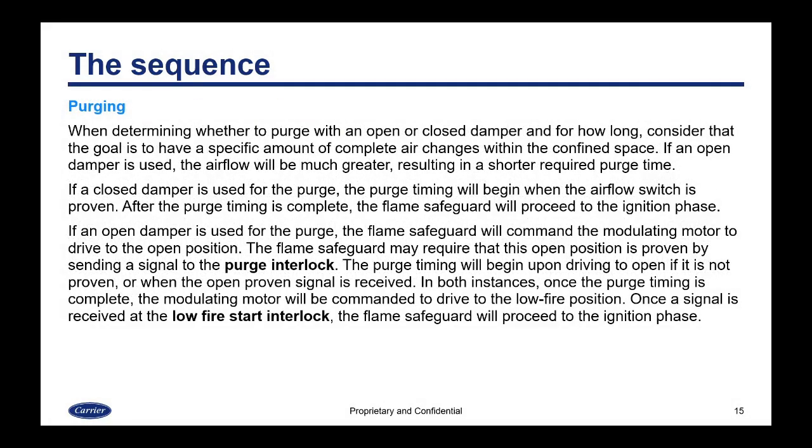When determining whether to purge with an open or closed damper, and for how long, consider that the goal is to have a specific amount of complete air changes within the confined space. If an open damper is used, the airflow will be much greater, resulting in a shorter required purge time. If a closed damper is used for the purge, timing will have to be longer, and it will begin when the airflow switch is proven. After the purge timing is complete, the flame safeguard will proceed to the next phase. And the reason a closed damper needs to be longer is less airflow is moved when the damper is closed than if the damper is open.